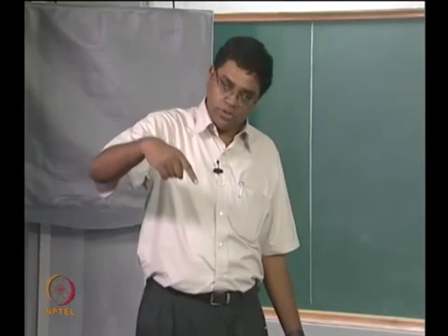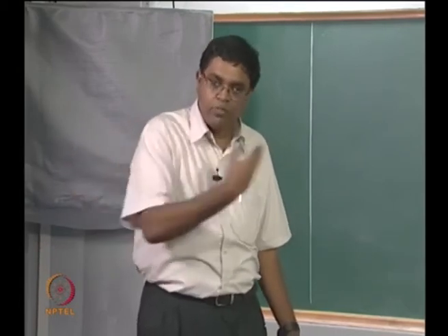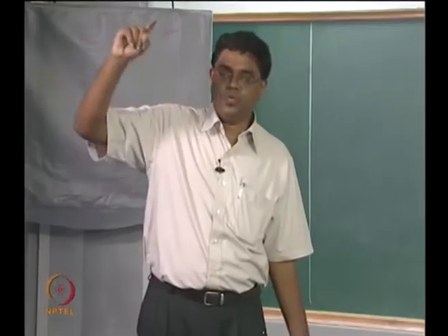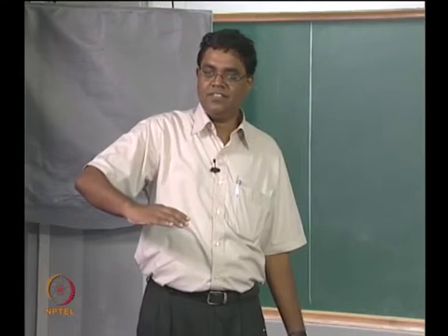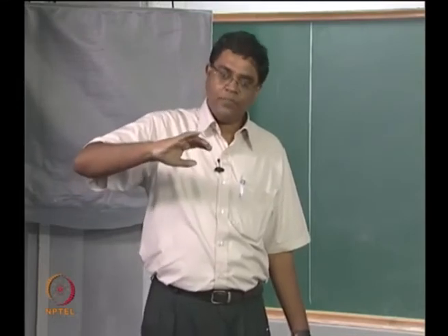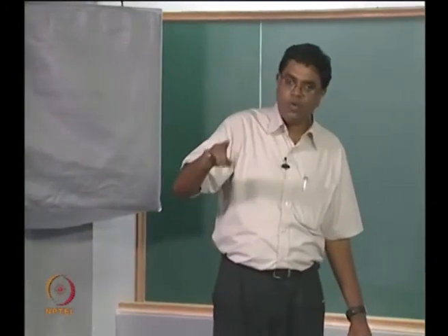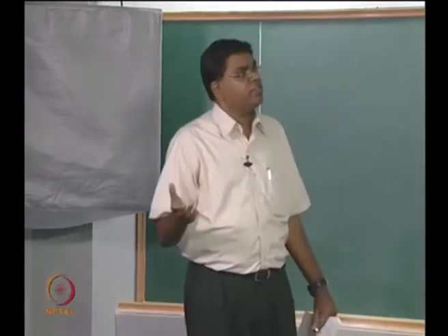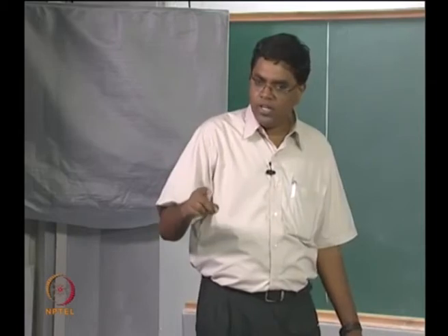If you now had two species equations and you assumed a non-unity Lewis number, all right, but the Lewis numbers were equal, right, you now have two species equations which are still linear, where you can still form the coupling functions, alright, and then you have the equal Lewis number for each of those still sticking together. It's only that you can't make it look similar to the energy equation. So as far as the species equations are concerned, they can begin to look similar, right? And I am still saying I am not having a unity Lewis number, I am having non-unity Lewis number, but non-unity but equal, you see. So there are such conditions. There are also other situations that you can deal with, like saying one of the Lewis numbers is equal to 1 but the other Lewis number is not equal to 1.